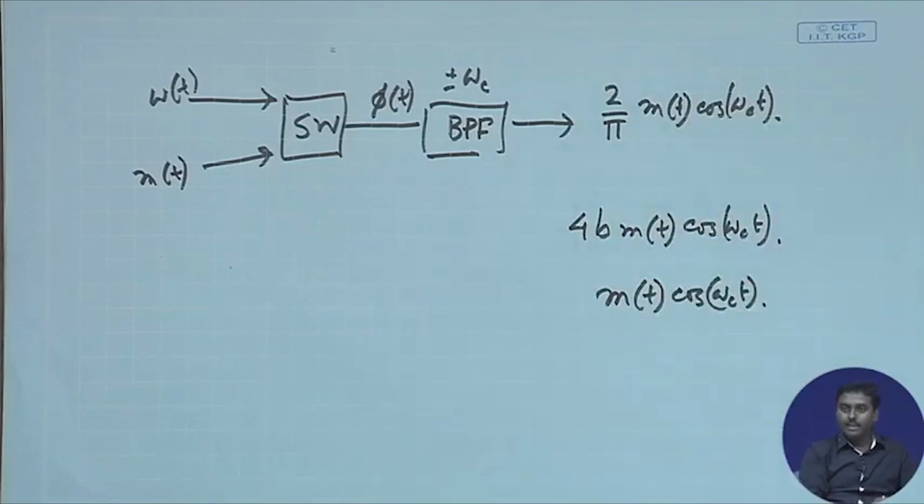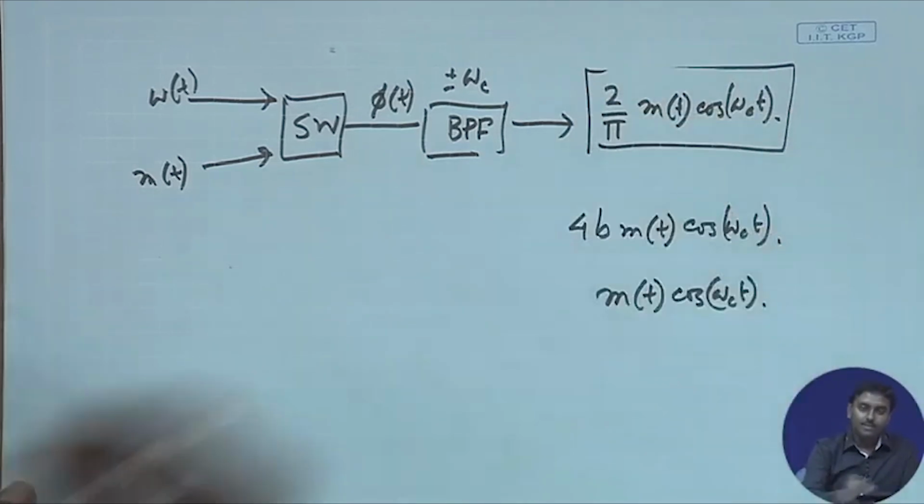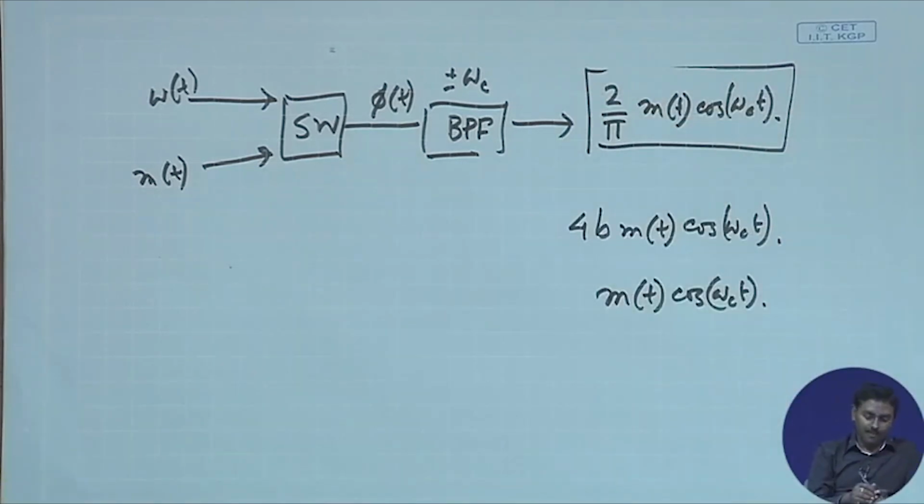So, what is happening if you just carefully see, especially this one, when I am doing multiplication, think about my power. Most of the power, because it had the infinite Fourier series representation, many parts of the power have gone to 3fc, 5fc, 7fc and all those things.